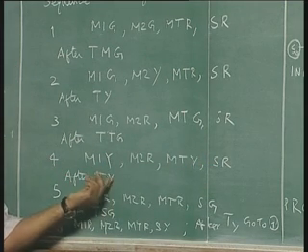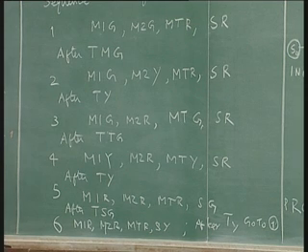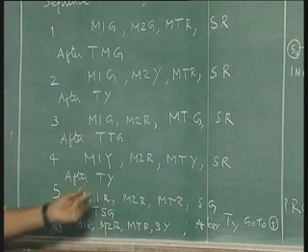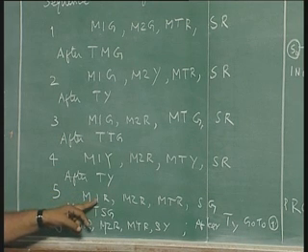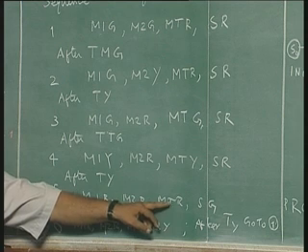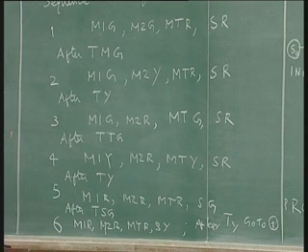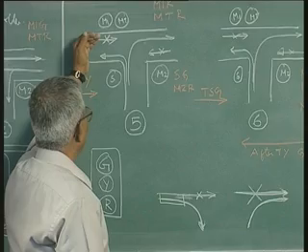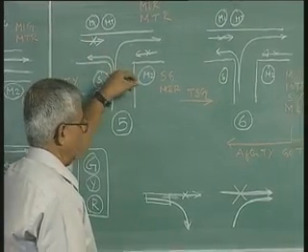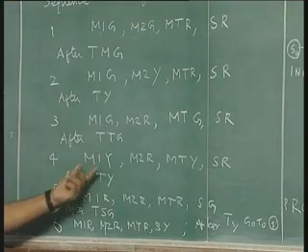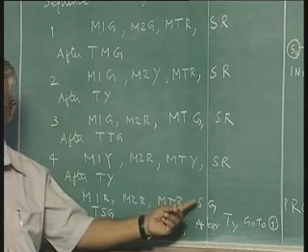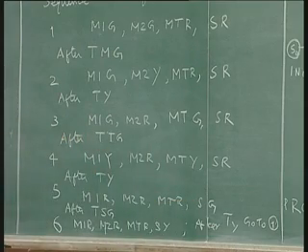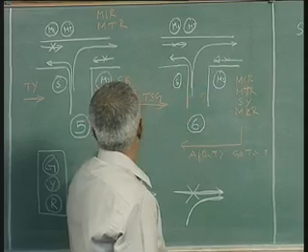This condition provides for a time of Ty, the time for which the yellow signal is defined. At the end of Ty, both the main 1 and the turn signal from main become red. That means we are cutting off the traffic from left to right as well as cutting off the traffic from main to side. M1 red, MT red, M2 is anyway red, side is allowed green. That means this is the first and the only time side traffic is allowed.